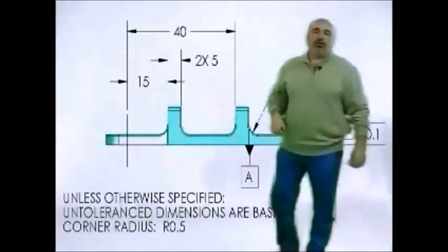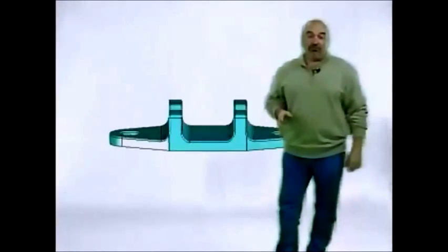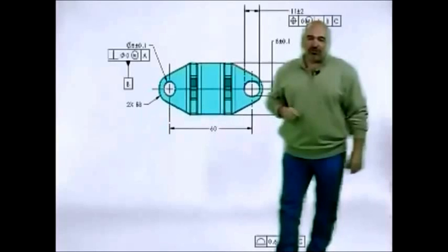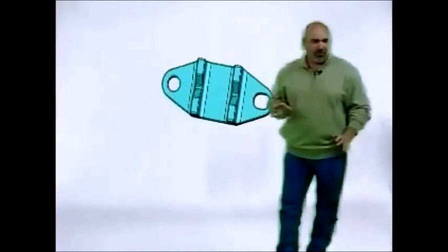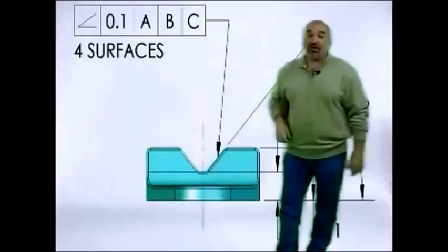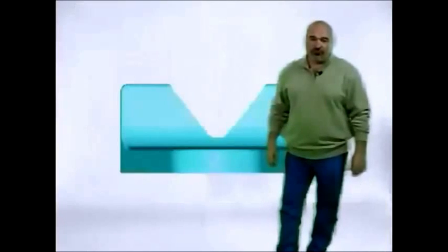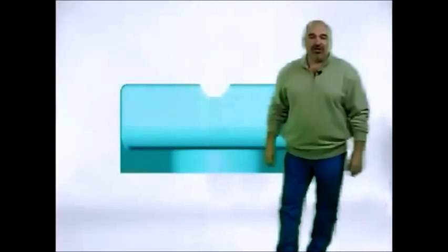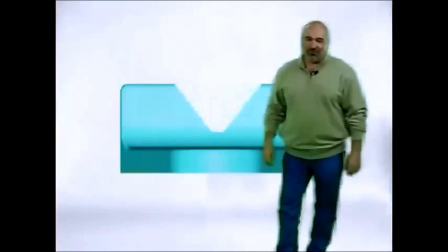A common error on a drawing is to apply only angularity to features and believe the location is controlled. Position locates features of size. Profile of a surface is the only geometric tolerance that locates surfaces. The orientation tolerances of perpendicularity, parallelism, and angularity never locate features.